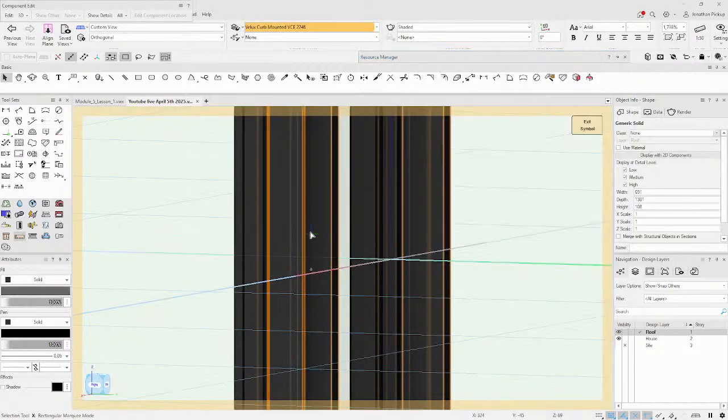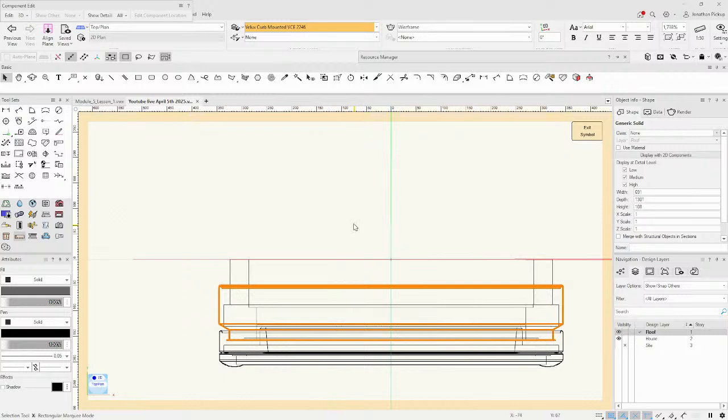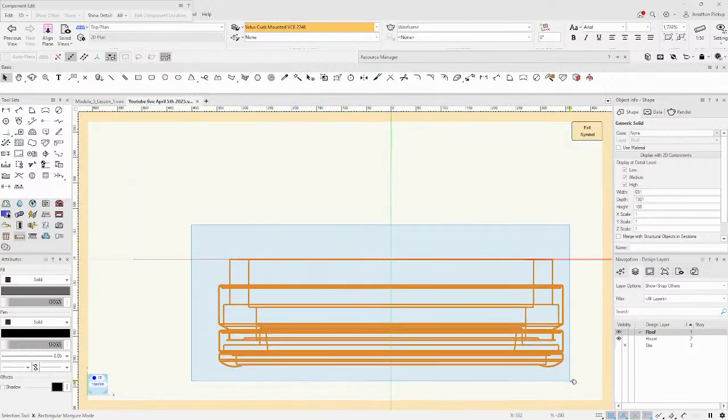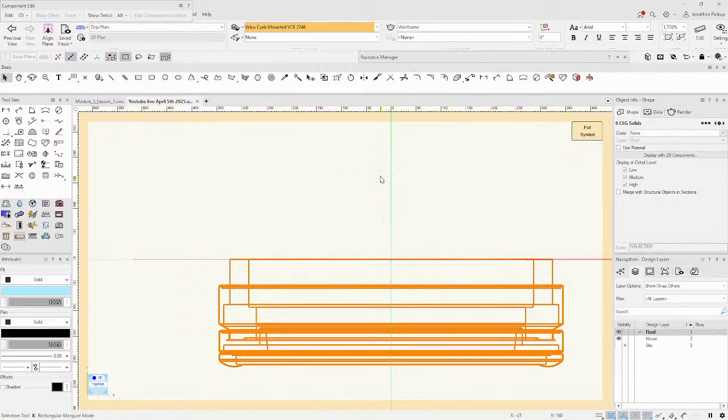Edit the 3D component. So back to a plane view, top view. I'm going to work in a plane view. I'm going to select all of that stuff there, and I'm going to use my move by points tool. I use move by points a lot. Maybe we shouldn't in this case. Or I can use my 3D dragger, which is really handy because you can move this to a specific location. So let's move it to there.